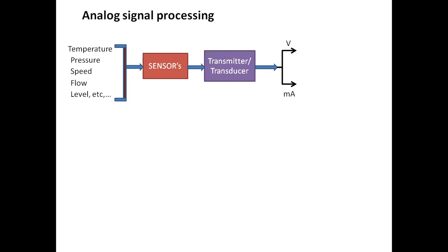If there is a wire cut, you will also get 0 as a value, so we cannot identify what the reason is. Okay. So these signals can be voltage or current, whichever we are selecting. For shorter distances, we use voltage, and for longer distances, we use current.